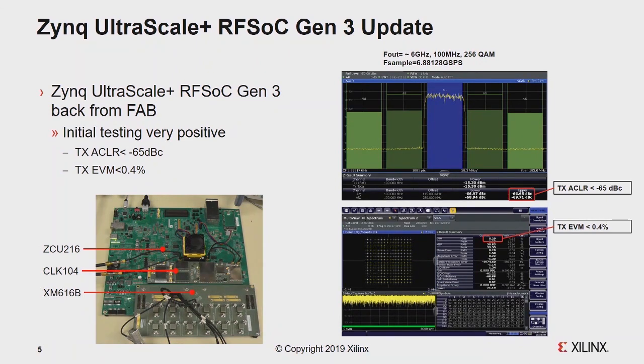And then we actually bring the RF signals out via an FMC type connector, which actually works to 6 gigahertz. And then we have a daughter card we plug on it. It's the same concept we use for the ZCU111. And this particular board, you can actually bring out all 16 DACs and 16 ADCs via these little connectors right here. They're called Carlisle connectors, and then they're cables. So you can actually bring them out, and then they're differential, so you can then run them back into balance or do whatever you want to do. Very convenient. So depending on what your use case is, you can change what it is.